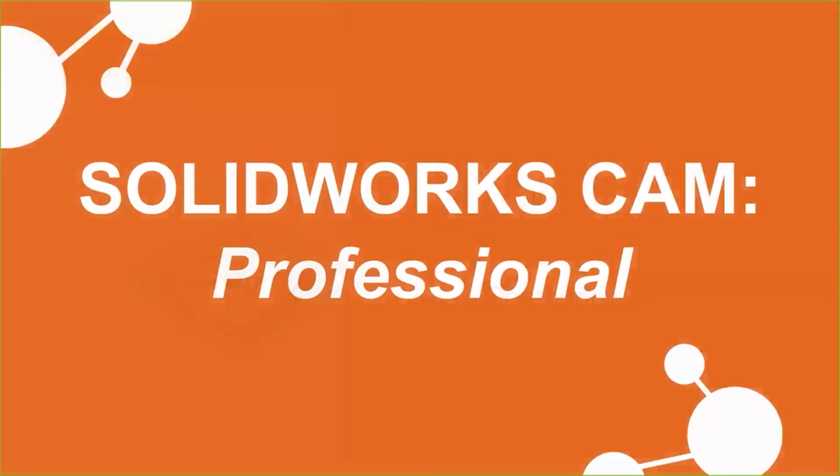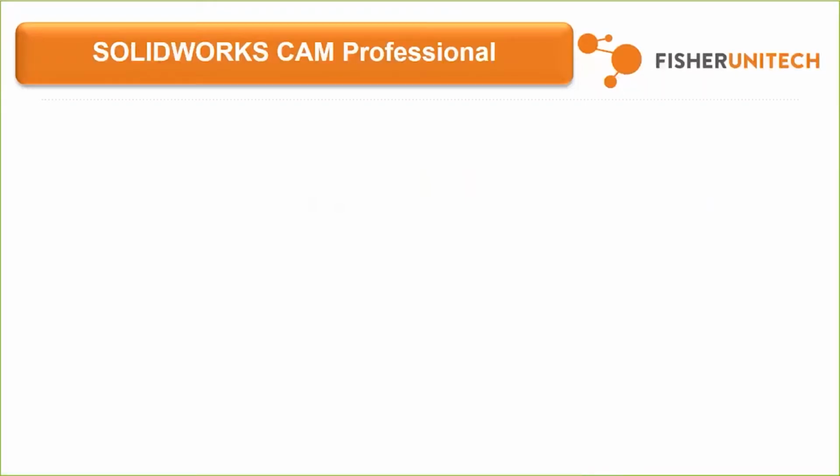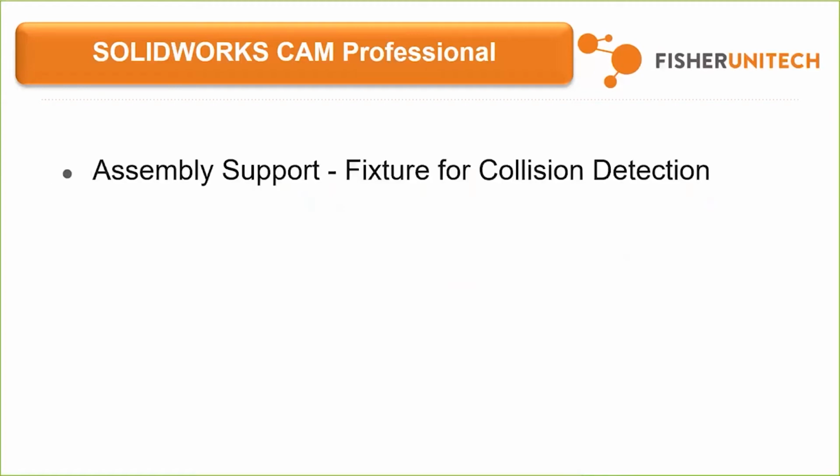So now let's transition. We'll talk about SOLIDWORKS CAM Professional. Within SOLIDWORKS CAM Professional, you get everything that's included within SOLIDWORKS CAM Standard, plus the ability to machine assemblies as well. So this adds, you can put fixtures in here, you can put your vices in here, and you can check for a collision between those as well.